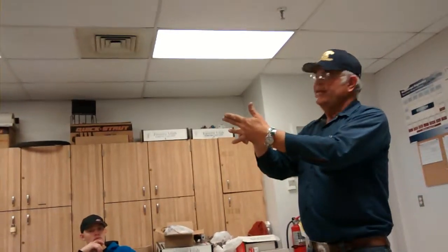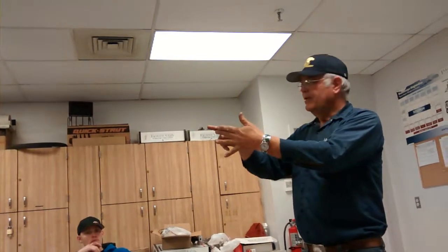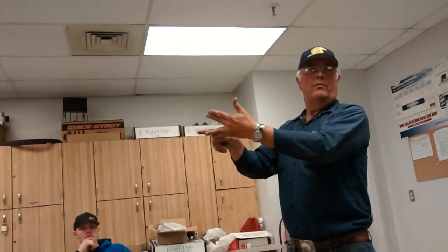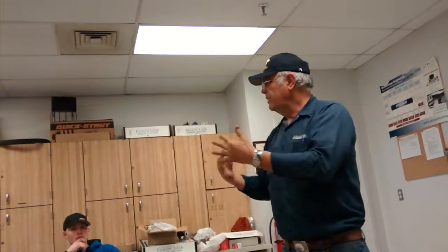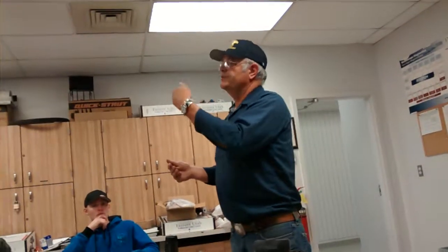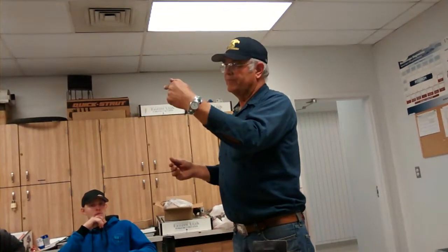You're probably back here to this one, right? If it only affects 2 of them, then we need to go somewhere else. And a lot of times you're going to find that these 2 end up with the same ground, and maybe with your blower motor too, because of where they're located on one lug. And so we also check the ground side, because the power feed side of the series may be different from the ground feed. We always check power and ground.